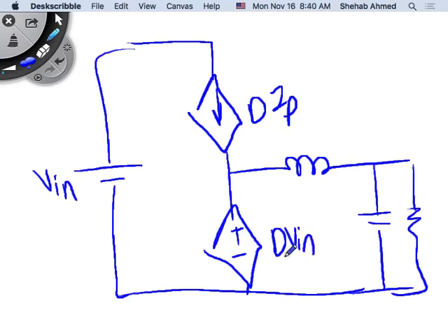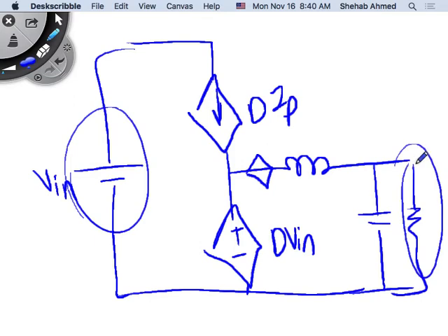And if you want to include the effect of losses, because again, remember we have a diode as well here, right? If you want to include the effect of losses, we would typically include it here as an opposing voltage. So for example, remember, everything we're trying to do is convert voltage to voltage, right? I'm taking my input voltage and converting it to an output voltage. Or in the boost converter, it's the opposite, taking a lower voltage and boosting it. In the buck-boost, but I'm converting voltages to each other.